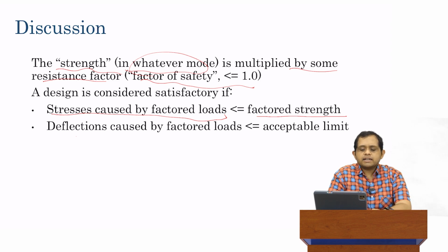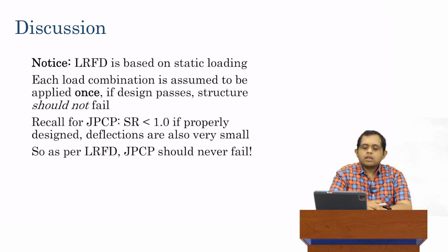And in LRFD then, a design is considered to be satisfactory if the stresses caused by the factored loads are less than or equal to the factored strength. Furthermore, the deflections caused by the factored loads must be within some acceptable limit, and that acceptable limit is specified in various design codes. That's the general idea behind LRFD design. I'm sure all of you either will or have studied it as part of your civil engineering curriculum.